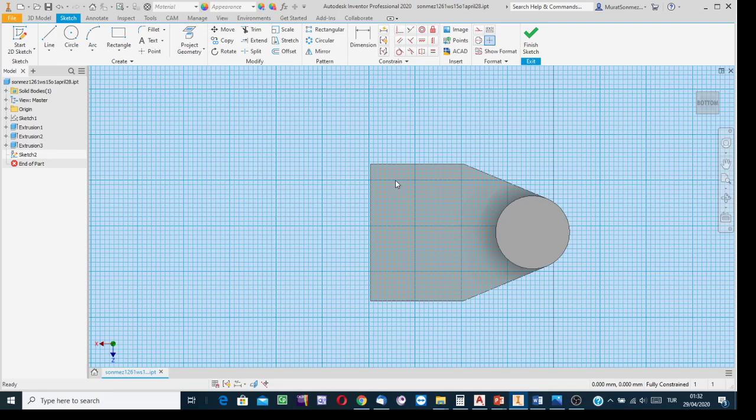To be able to create the sketch in the correct size and at the correct place, I need to indicate this as the reference and this one or that one as the shoulder, if you're going to apply the trimming technique or if you're going to input a dimensional constraint.